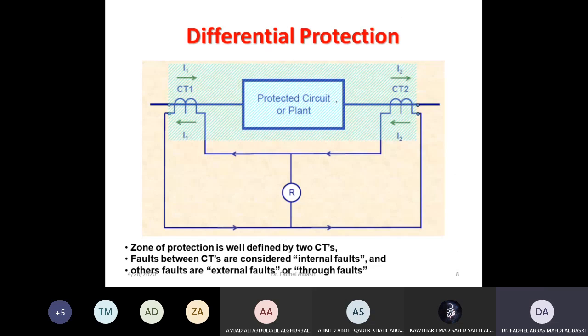Now in this case, if I have a relay protecting a differential relay, the principle is something like this. Suppose this is a line also, and I have a current flowing in the primary side. At the sending end side it is I1, at the receiving side, the current at the secondary will be I2 over CT ratio